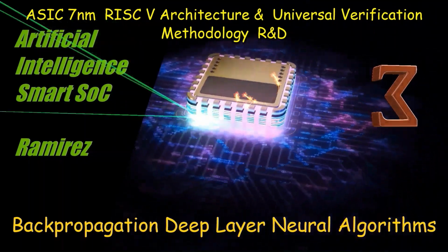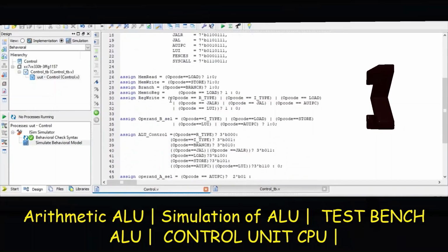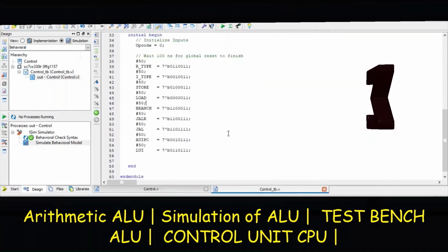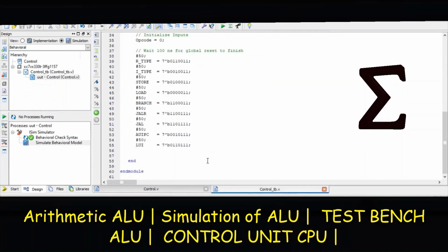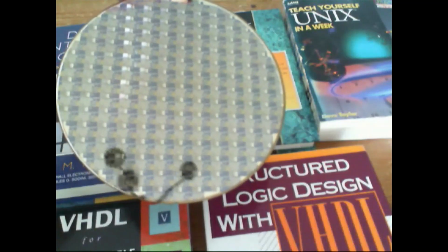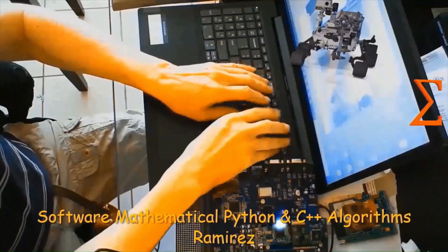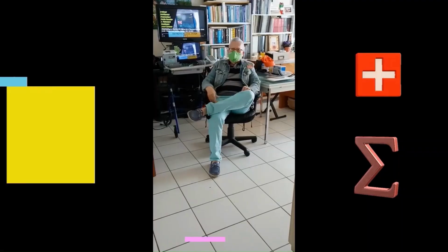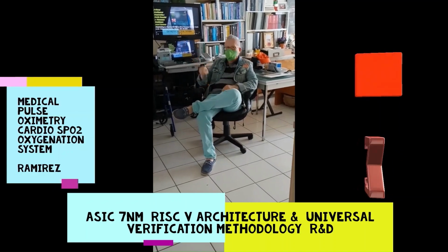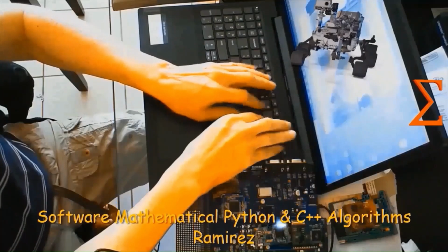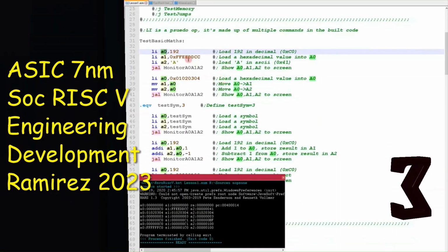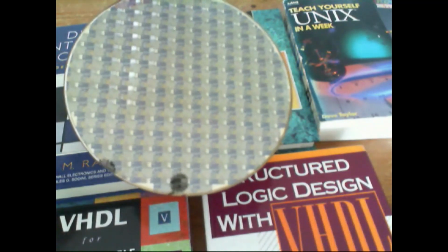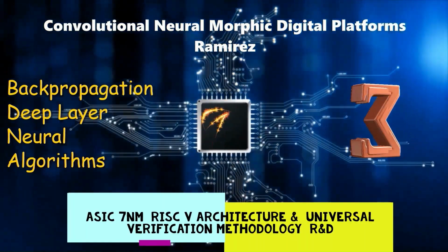At the top level HDL, I successfully determined the configuration and generated the top level HDL design. In parallel, I completed and generated synthesis scripts, synthesized with reference to the library, provided scan insertion, ATPG fault simulation, and also performed the final timing and power analysis. Also in parallel, I provided functional verification with a reference simulator, developed and ran multiple test configurations, and measured test coverage.